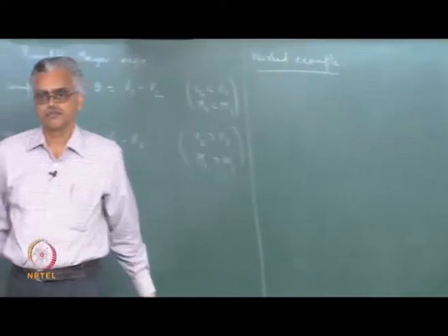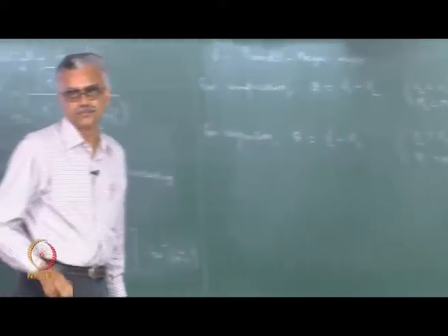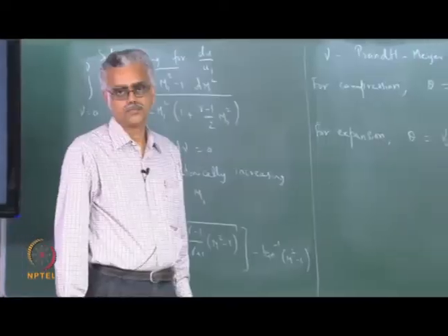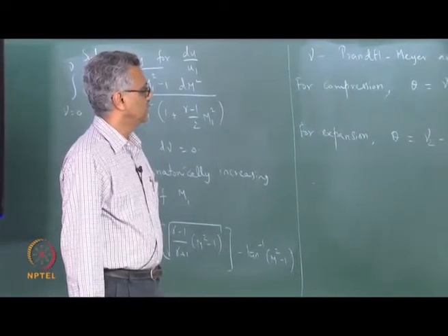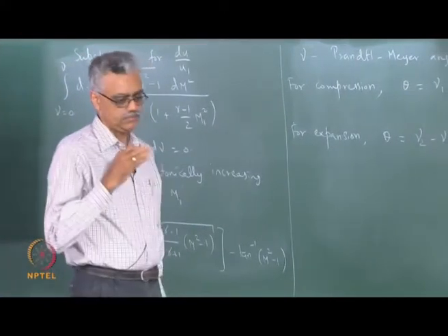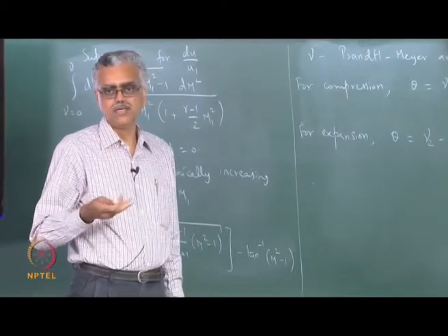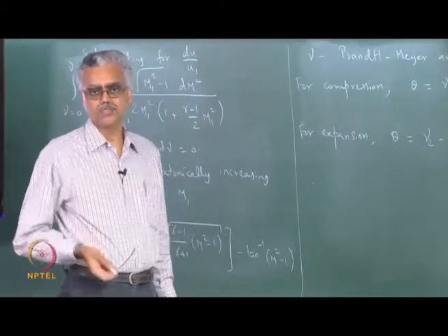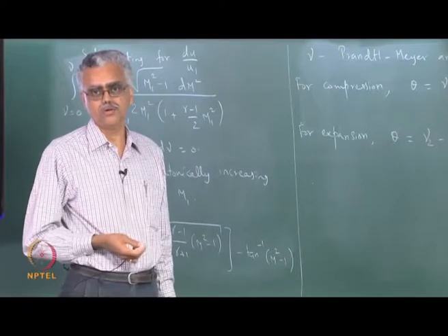Yes. Suppose the flow over a flat plate is a supersonic flow. When that flow leaves the plate, what will be the Prandtl-Meyer angle at that particular point? The flow turning itself is not defined there, so the flow is going to be much more complex than what we have been doing so far.